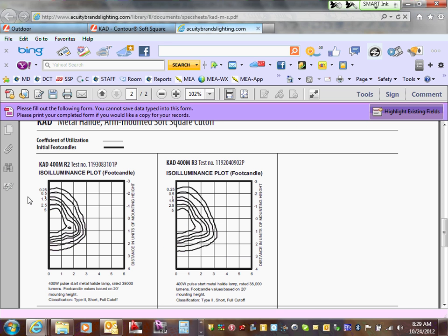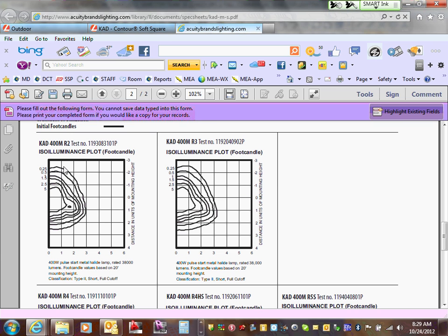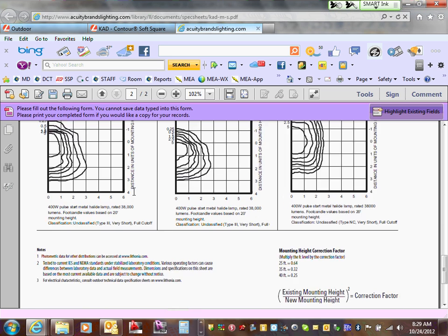Now right underneath it, can you guys see the ISO illumination curve for these fixtures? If your fixture is sitting right here, this is how it's going to distribute the light around it. This will be the topic for tomorrow when we do ISO. These curves are the lumens per foot candle on the parking lot. Can you guys see 1, 2, 3, the distance and the distribution of the light in this parking lot? Again, thank God, Lumen Visual has all these curves. Remember how you would drop it and it drops with that curve? That's what they're talking about. You drop that curve, overlap them, done. But this comes for each one of these fixtures.